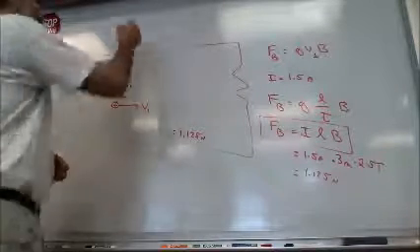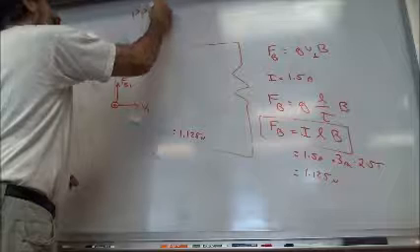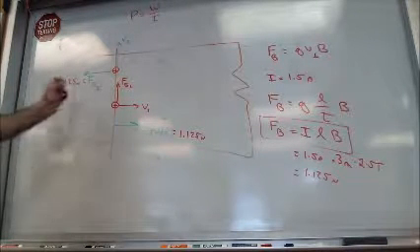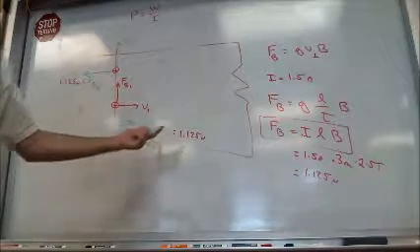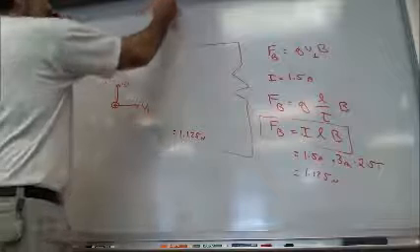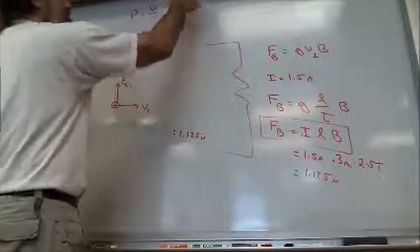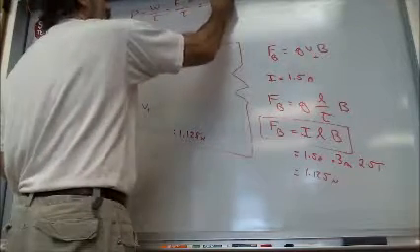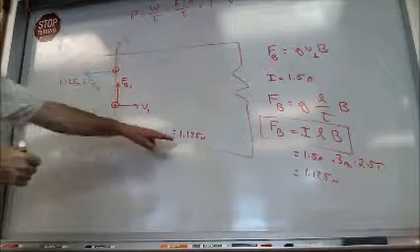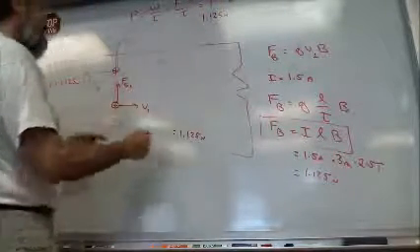Power. Who remembers the formula for power? Work per time. Remember running up the stairs? Whether you're running up the stairs or pushing a wire at a certain speed with a force, it's force times the distance divided by time. What is distance over time? So we could just say force times velocity, couldn't we? How much force am I applying? 1.125 newtons. At what velocity?